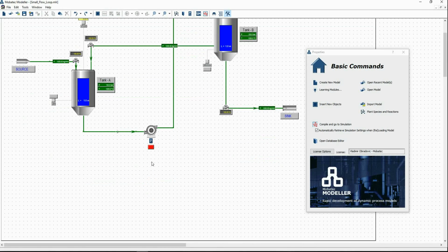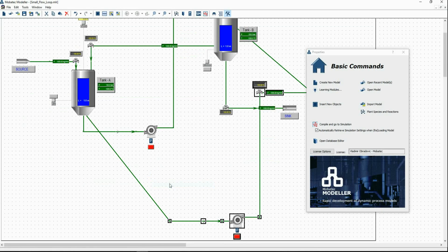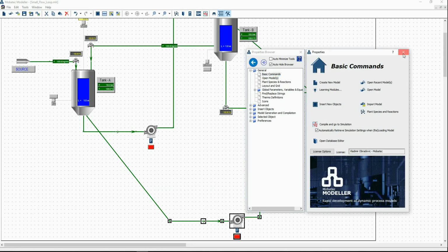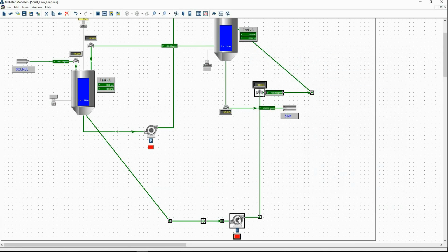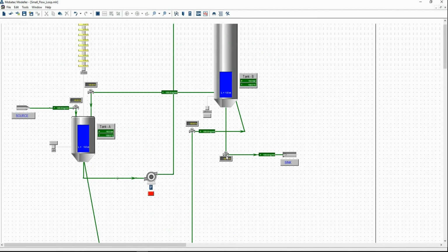Click right mouse click on the empty work surface and choose Paste Keep Connections. What this will do, as you can see, will copy the selected items, but will keep the connections origin and target point connected to the systems that were before the copying. Now we can adjust easily the position of these lines.